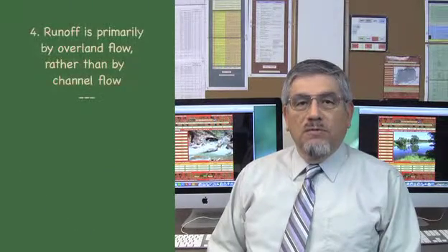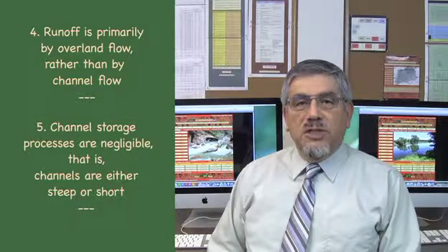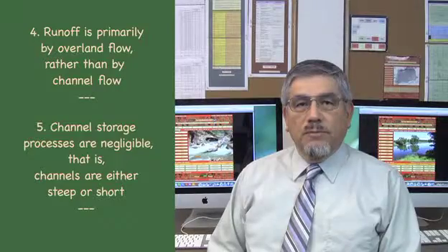4. Runoff is primarily by overland flow rather than by channel flow. 5. Channel storage processes are negligible, that is, channels are either steep or short. The runoff response of small catchments can be described with relatively simple parametric methods. In certain cases, a more complex overland flow analysis may be warranted.